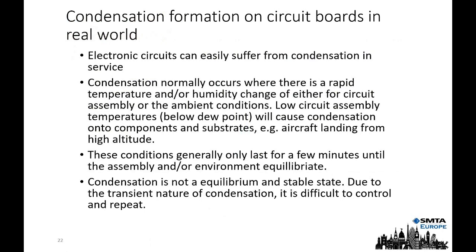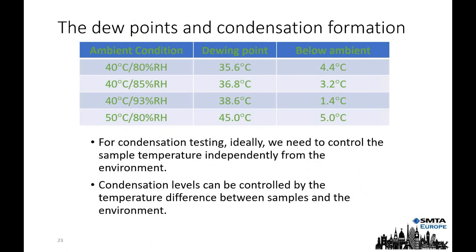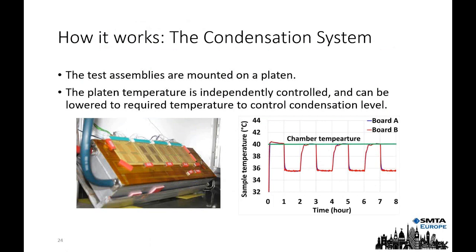And the existing condensation test methods have not been ideal to really give us a true repeatable test. So what one of the engineers at NPL put together is a condensation test which controlled the amount of condensation that is actually coming onto the surface of the printed circuit board and onto components. And by controlling the temperature of the printed circuit board assembly and the environment, they were able to differentiate the amount of condensation that actually takes place.